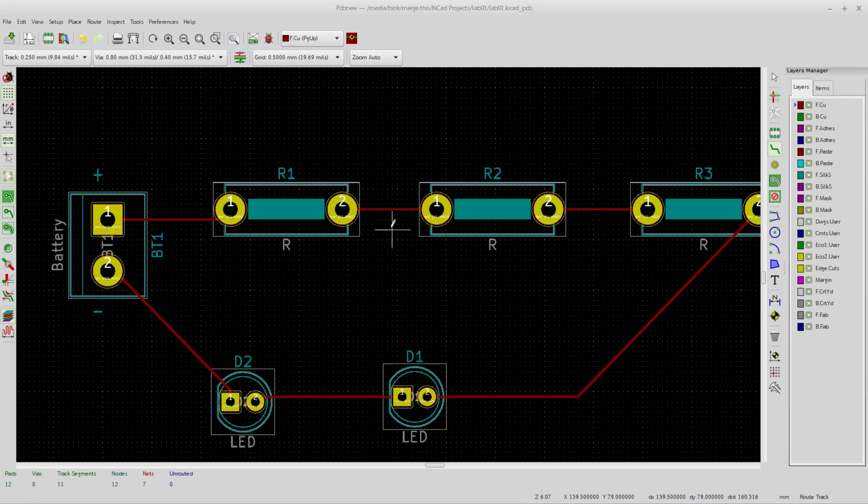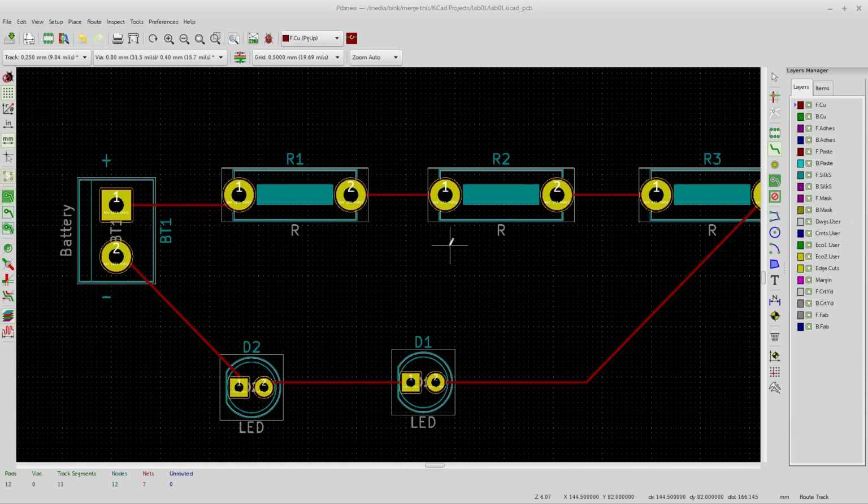But typically, if I needed to get across from here to here, I could drop a pad right here. I could drop a pad right here. Basically, I could put the SMD resistor right over the top of this line right here. So one pad's on one side, one's on the other. You wire into that, you wire into that. Your design rule check doesn't throw a fit because it looks like a component that belongs there is there, and that's what it's supposed to do. And you create yourself a little bridge right over the track. So that's a pretty cool way to do that.